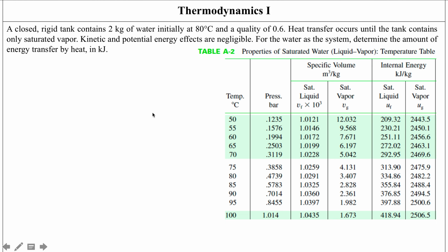Let me just make that real quick. You've got this curve, and in the pressure table you've got a value of 1 bar given to you. In the temperature column right next to it, you're going to have some temperature, which is going to be the saturated temperature.